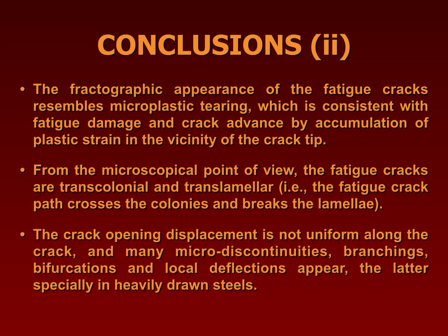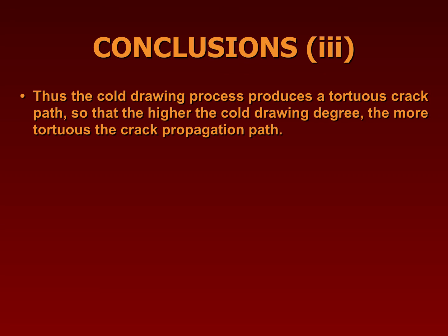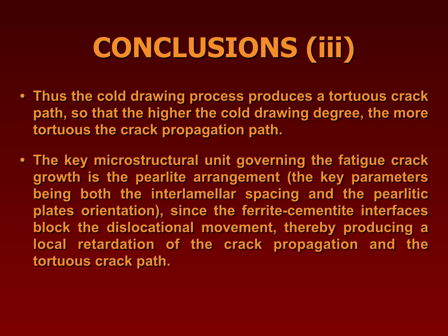The crack opening displacement is not uniform along the crack, and many micro discontinuities, branchings, bifurcations, and local deflections appear, the latter especially in heavily drawn steels. Thus, the cold drawing process produces a tortuous crack path, a tortuous microcrack path, so that the higher the cold drawing degree, the more tortuous the propagation path.